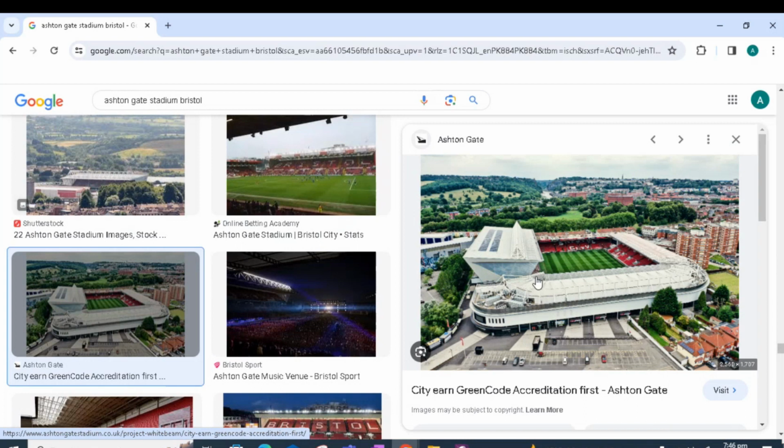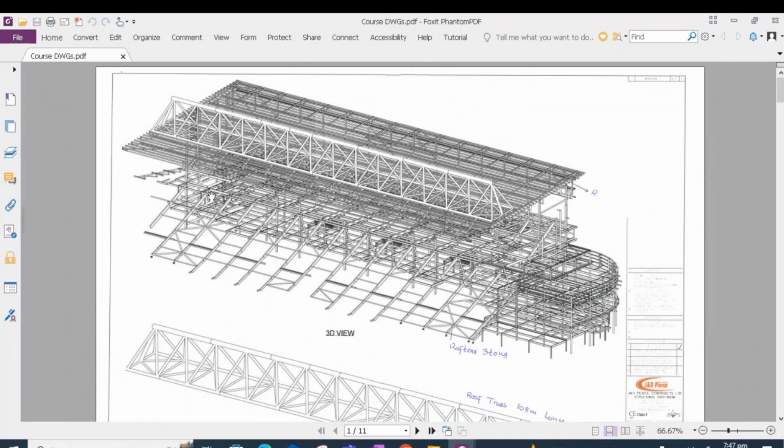These cantilevers are tied with each other in order to have an integrated structure. In this drawing, we can see the same lattice girder being supported by the framing at the gable end, and the lattice girder is actually supporting cantilevers underneath. This lattice girder is almost 100-meter long.